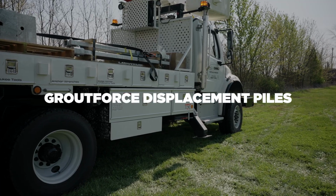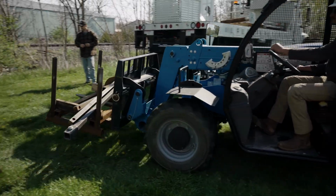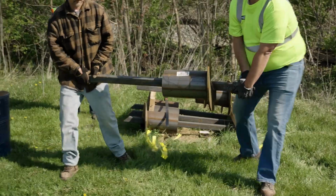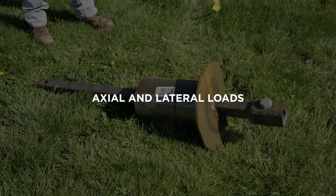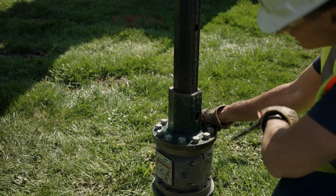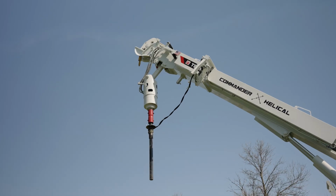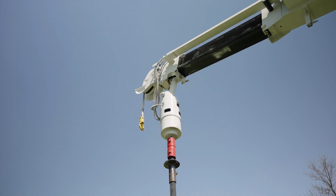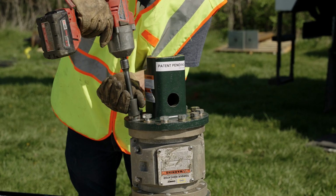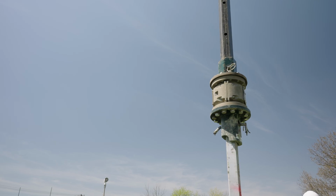The Chance GroutForce Displacement Pile, or GDP, is a patented foundation solution excellent for use in loose to dense sand or soft to firm clay. GroutForce piles provide significant axial and lateral load capacities and can be installed to over 500 kip. The solid steel shaft is surrounded by a grout column, which increases diameter and frictional bond, so the shaft length may be reduced by 50% or more versus other pile types while maintaining its high ultimate compression strength.